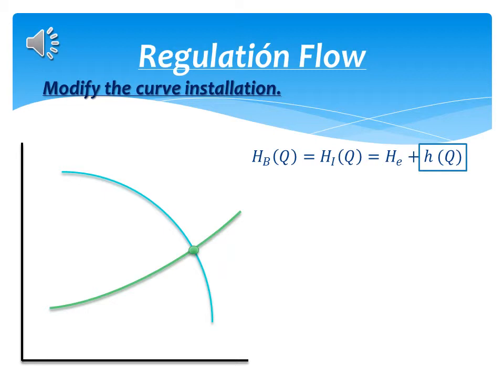Let's separate the losses into two parts: losses caused by the throttle valve and the rest. Within the singular loss, kV is a singular constant, which depends on the Reynolds number, the roughness and diameter parameters, which we are not interested in changing, and the degree of openness, which is simpler to change in a pipe, for example.